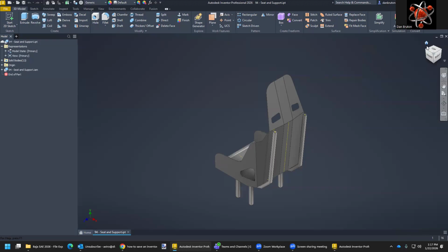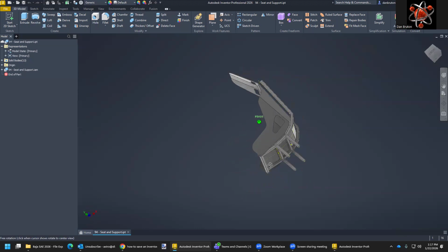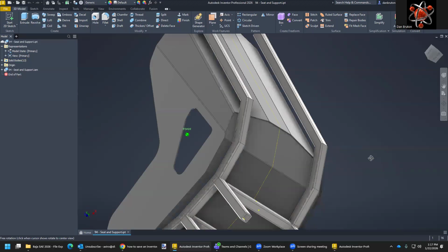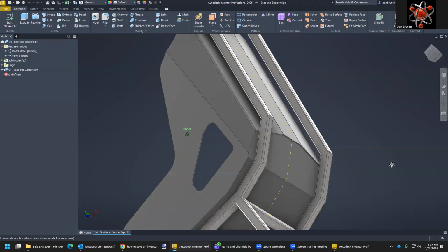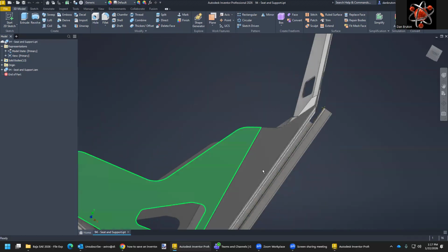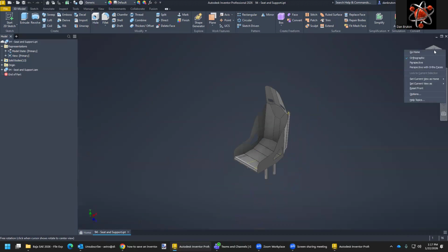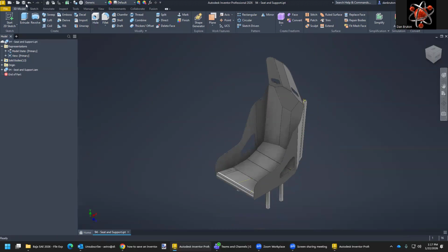All right, and it looks like it again redefined what it thought should be home. So this will be the assembly that we will eventually then pull into the roll cage assembly. It looks like I will get a little bit of gap right there, which is expected because of that angle. That'll be good to know as we move forward. The benefits of doing this in modeling software as opposed to trying to weld it right away. Right click, set current view as home, home, and save. This is what I want you to upload to D2L.